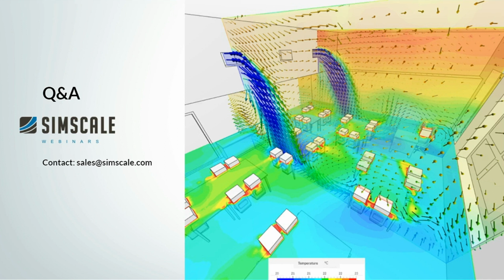Thanks, Richard. There is another question on how to check the mesh quality. So that's again an interesting question. Within SimScale, as Richard mentioned, the main vision is to make sure the tool is easy to use. Even if you don't have expertise in meshing or setting up a simulation, SimScale guides you with automated solutions. So you have automated algorithms working in the background that will mesh according to your imported geometry. And if you're really interested in checking the quality, we do write out a lot of mesh quality parameters that you can take from the meshing log.